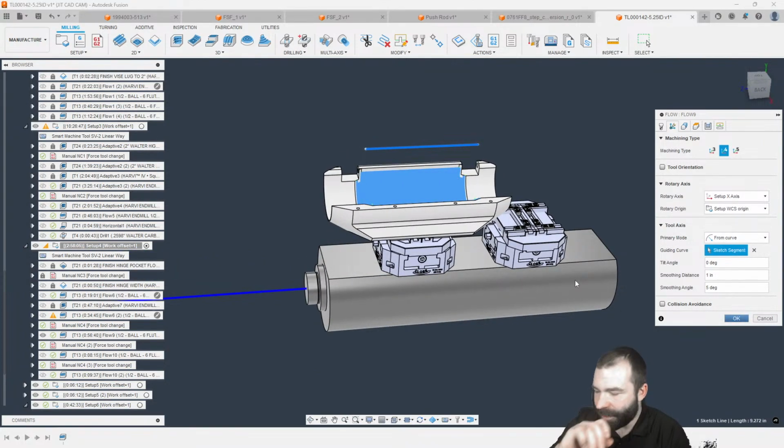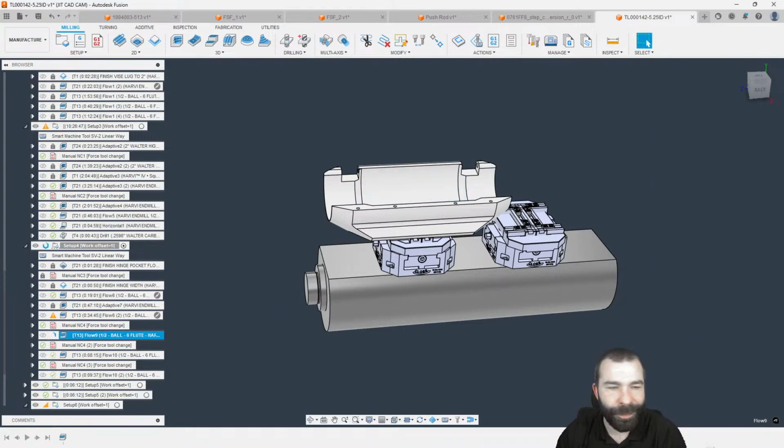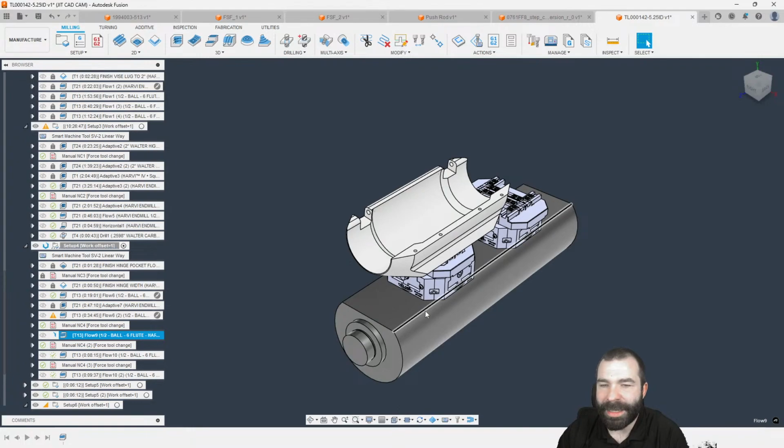And if you guys have never seen from curve or to curve or from point to point, it's really handy when you get into like a female cavity or something that's internal at the end of the day. Fusion's hating me right now. I'm recalculating your tool path. But we could also turn on the tool path simulation and I could show you guys how that works.